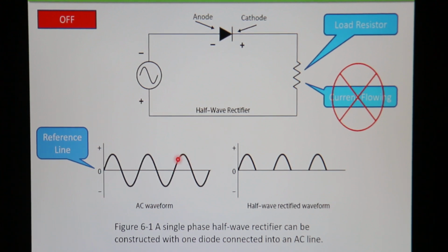And the RMS value is 0.707 of the peak. So whatever my peak value would be of this sine wave, I can multiply it times 0.707, and it would give me my RMS value. That's what you'll be reading with your circuit if you measured from a receptacle.